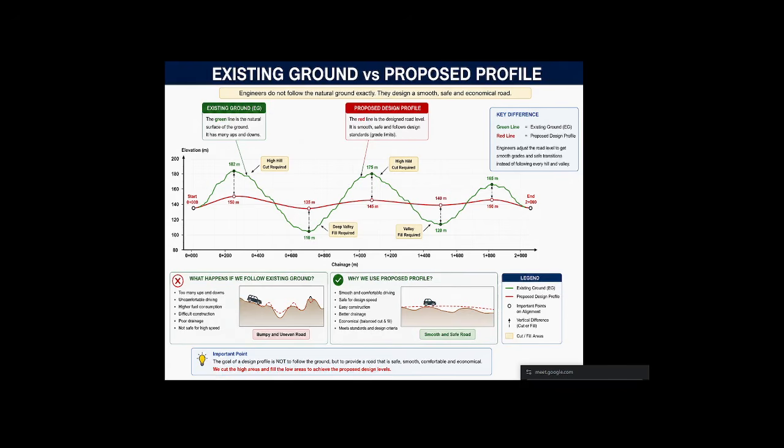Now, if we are talking in the sense of the descending grade, then what happens? If I give you the criteria, like the road falls by 3 meter, then minus comes, sir. If descending, minus 5%. Now I am changing the example. Like if we have a road that falls by 3 meter, and the horizontal distance you can consider as 60 meter. Now what is the grade?